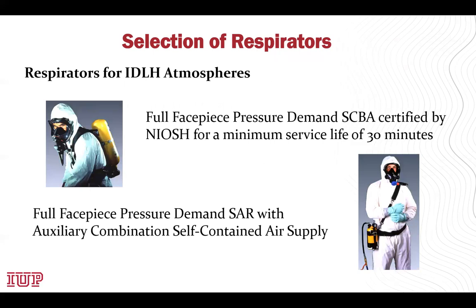For respirators for all IDLH atmospheres, you should have a full face pressure demand self-contained breathing apparatus certified by NIOSH for a minimum service life of 30 minutes, or a full face pressure demand supplied air respirator with auxiliary self-contained air supply.